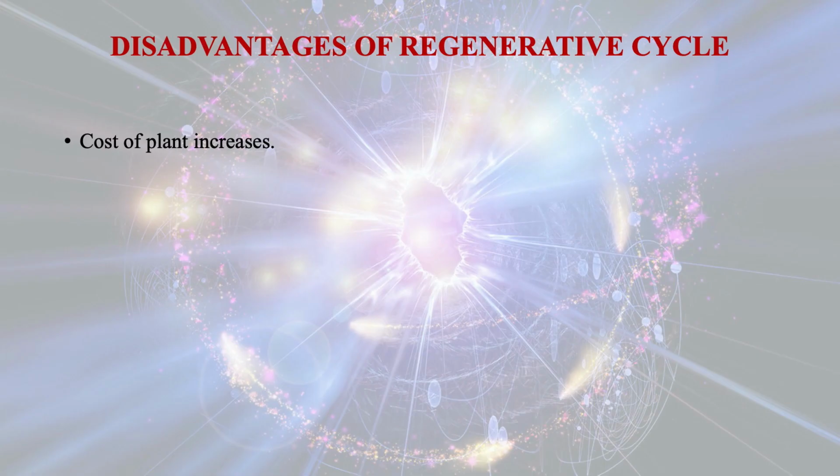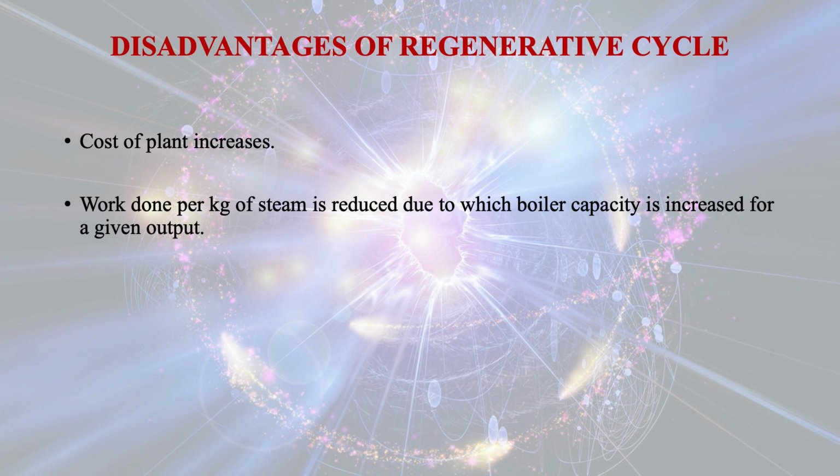The disadvantages of the regenerative cycle are: the cost of the plant increases, and the work done per kg of steam is reduced, due to which boiler capacity is increased for a given output.